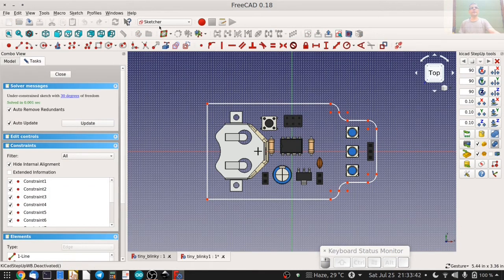That brings up Sketcher. And there are a large number of degrees of freedom because none of these have any constraints at the moment. For some of those elements for which we don't want to add constraints and yet reduce this under constraint nature of our sketch, what we can do is select them and use a toolbar icon that says lock, or create a block item that prevents those items from being modified or changed.